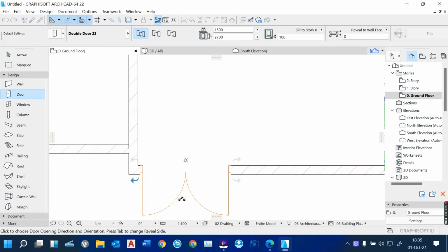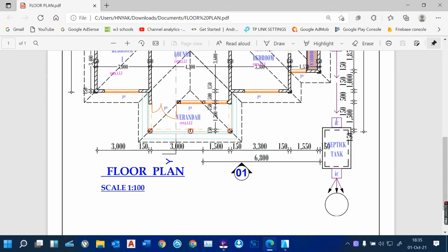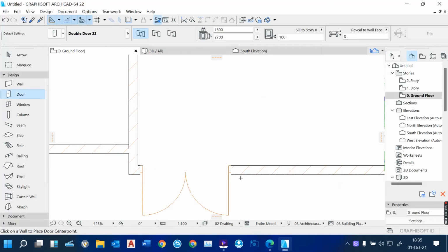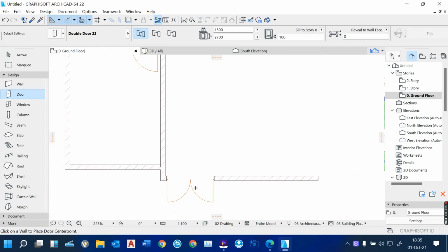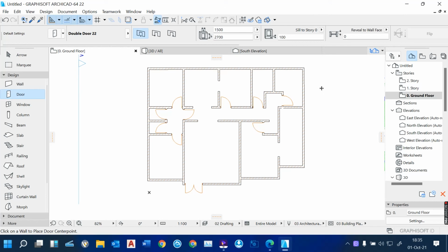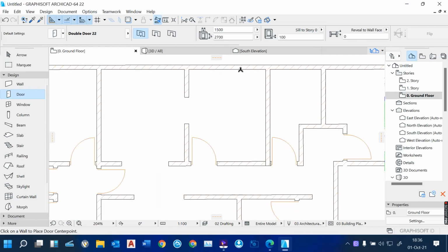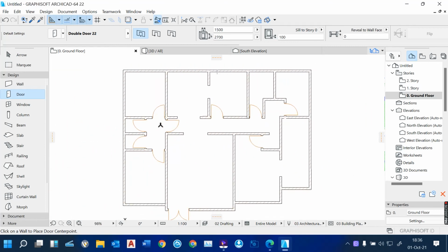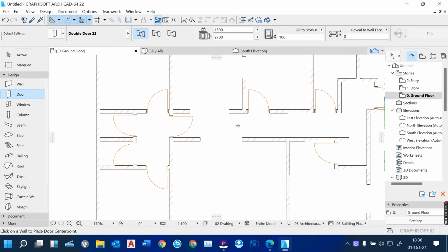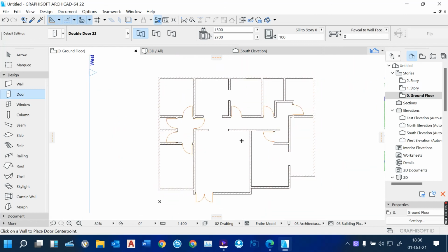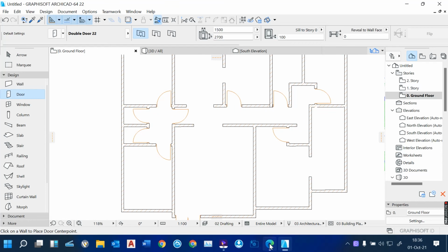For this new version, this type of door does not exist in our libraries, so we just pick this one because it also acts as our double door, the one for the entrance. We don't have a bigger door and a smaller door in 2022, but for other lower versions, we have that type of door. So generally, that's how we make a plan, place doors, trim doors, create openings, and also change the door and adjust the openings as per the project as shown here.